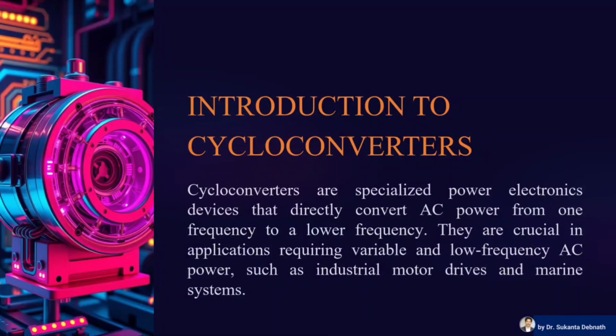Good morning. In this lecture, I will be explaining the introduction to cycloconverter. A cycloconverter is a power electronics device that converts an AC signal with fixed frequency and fixed voltage to an AC signal with variable frequency and variable voltage. This type of converter is mainly used in low frequency and variable speed applications, such as industrial motor drives and marine systems.